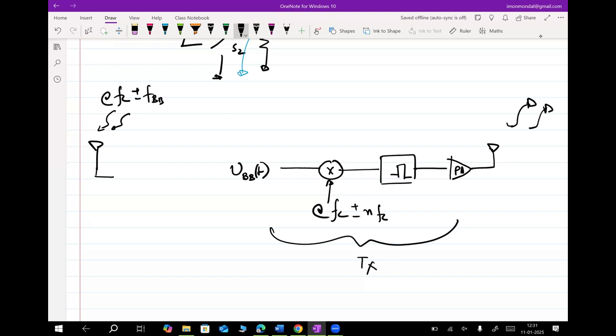The only reason we were at high frequency is because we wanted to send it out. Inside the chip, processing is not necessarily needed at FC. In fact, I would like to have processing at as low a frequency as possible inside the chip because it saves power. So the first thing to ask is, how do I receive it?